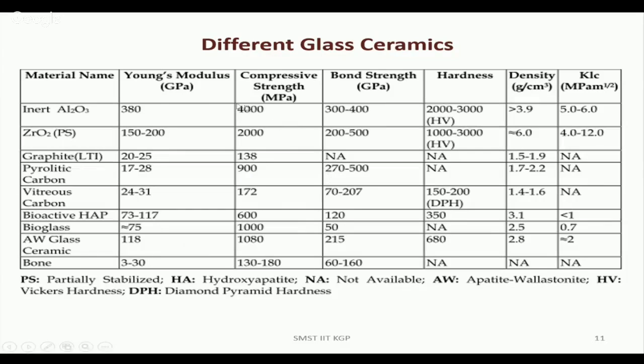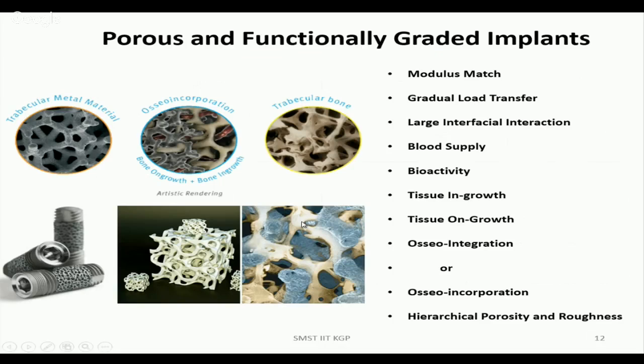So we have to consider the design aspect as well to address stress shielding issues. As I said before, again I am mentioning here, a functionally graded porous implant is the key, and you can see here Zimmer has developed these dental implants. You can see the surface has porosity. This porosity, pore size, and surface texture help with bone on-growth and ingrowth, and osteointegration and osteoincorporation.